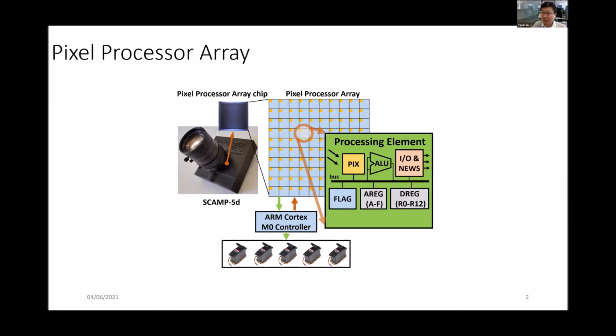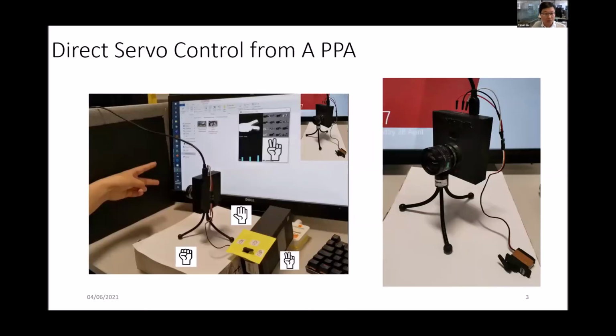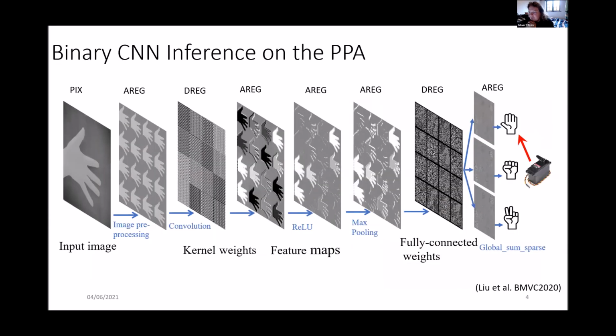Excellent. And actually, if we can extend to more servo motors, in that case we may need another power supply for more servo control because of the power. In the SCAMP, currently we just use the GPIO as the power supply for the servo. Cool. Okay. So I guess you need to have it as part of a bigger system if you wanted to be able to do more, right? It can't deliver enough power by itself.